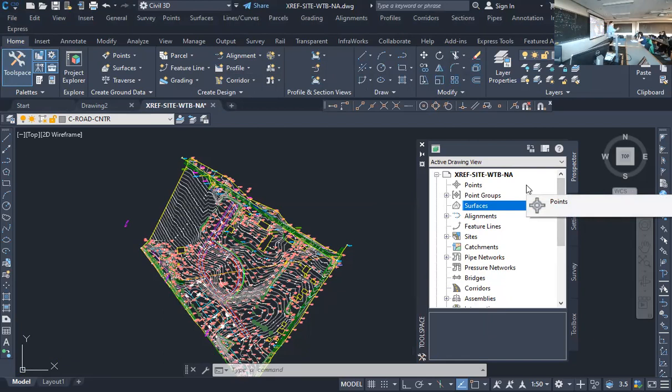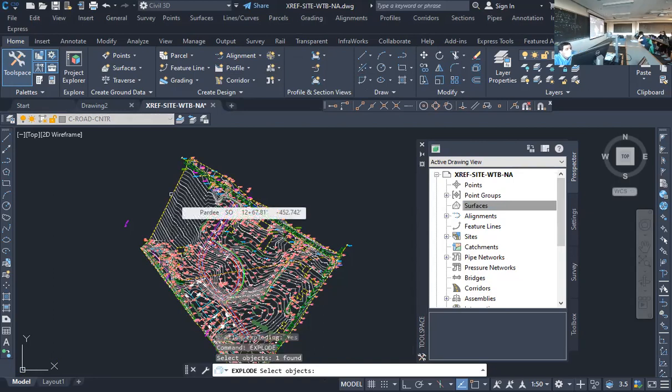It's like if I handed you my backpack. It doesn't see the pens that are inside the backpack, it just sees the backpack. So what you need to do is explode this. This is the next important step. Type out explode, just spell the word out, and then select the object. Then hit enter. Then you're going to wait.